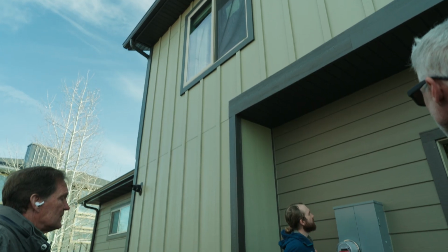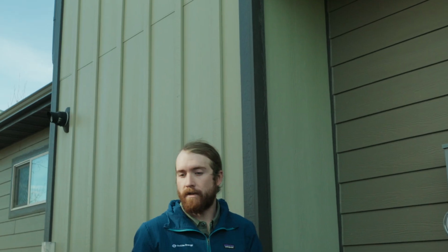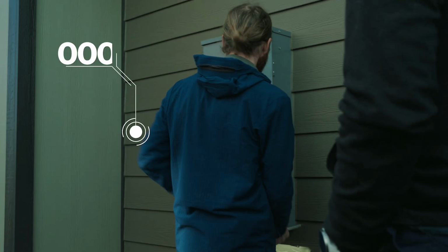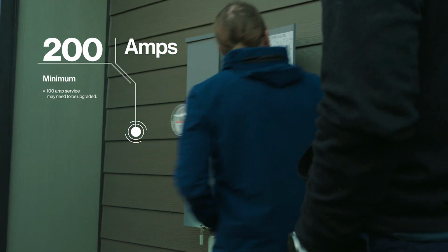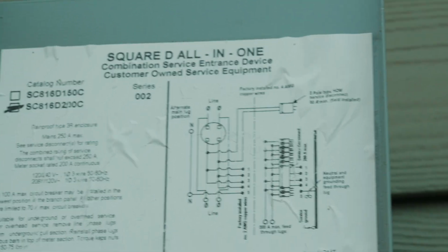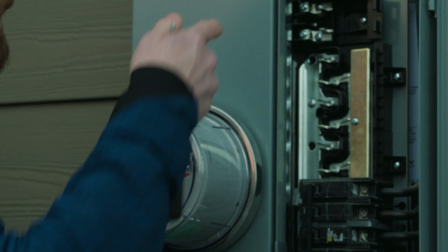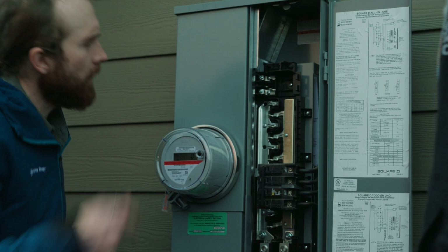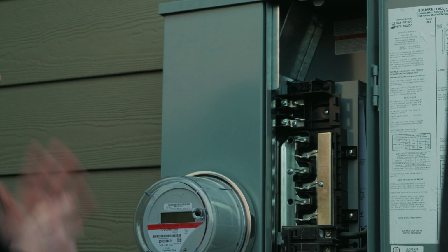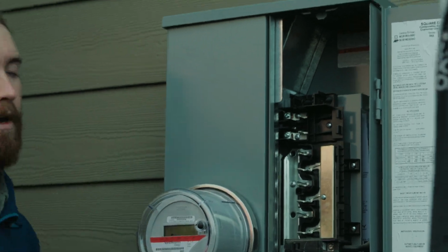The combiner box would go here, and that combiner box is going to be your gateway for communications and a disconnect switch, which then goes to this. 250 amp max, that's a really good sign, especially for future solar if you expanded your system. This breaker space right here is more than likely where the solar breaker will go. We will interconnect here at the service meter rather than backfeed a breaker in the main house breaker panel.